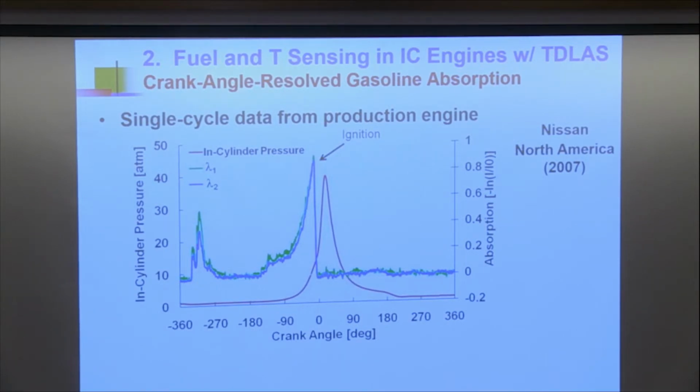I know what's happening. I took out several slides that dealt with the temperature sensor. So they wanted to probe what's happening near the spark plug. And the goal was, could we characterize the cycle by cycle variation in the fuel air ratio and relate that back to cold start emissions? So they're worried about the statistical variation in the exhaust of unburned hydrocarbons and tracing it back to how things are behaving by the spark plug.